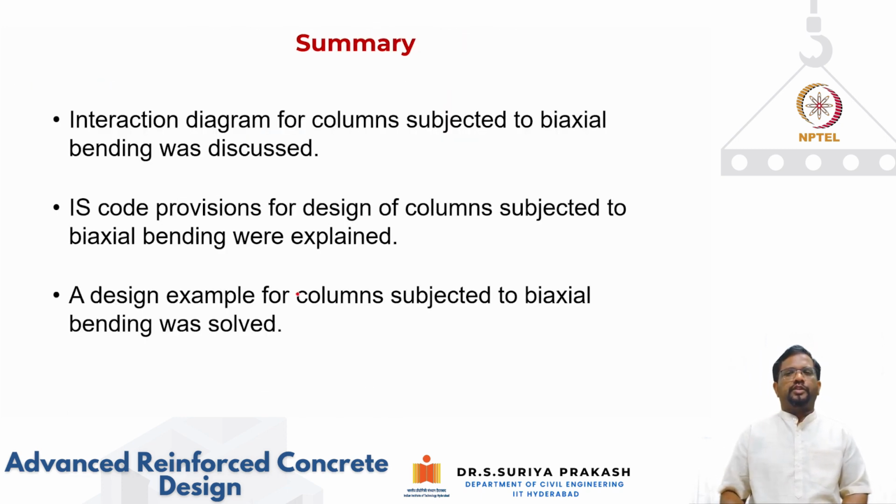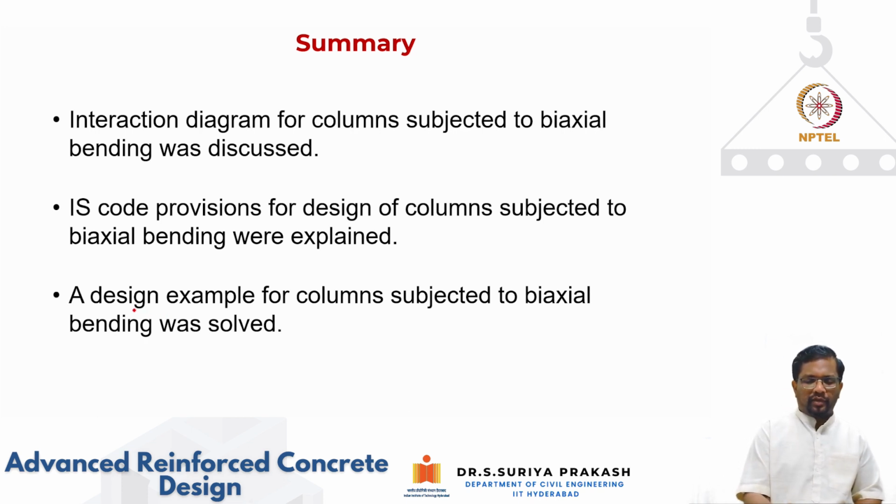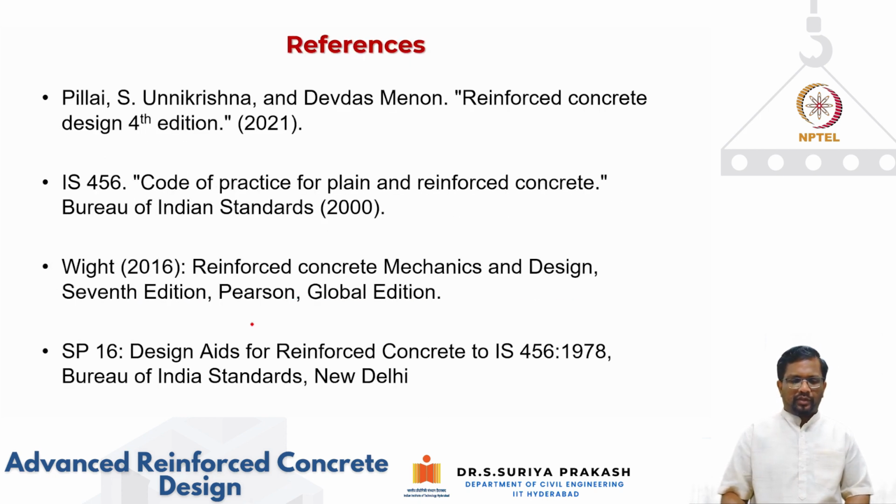All right, so let's summarize. In this part of the video, we discussed how the interaction surface is derived for biaxial bending. We also discussed IS code provisions for how to design for biaxial bending. Particularly, we talked about Bresler's load contour method, and we illustrated how to use SP16 and how we can do the design example for biaxial bending, right? These are the references that you can use for further study, and SP16 is readily available. You can download it from the internet, right?